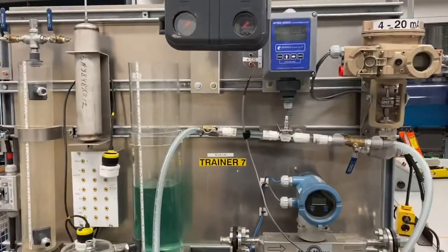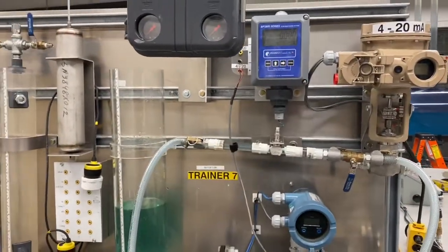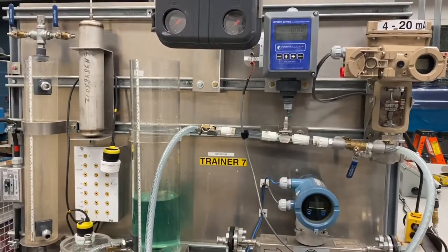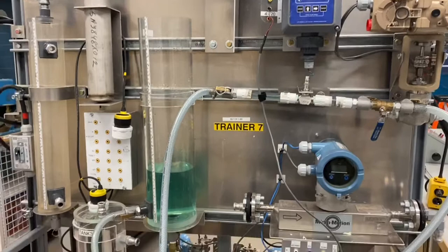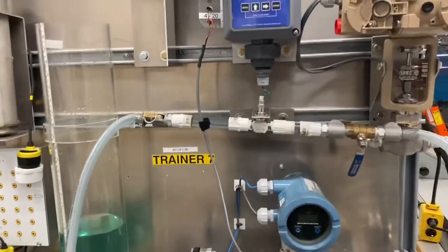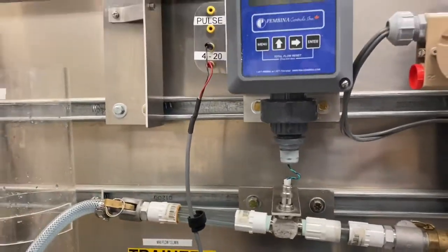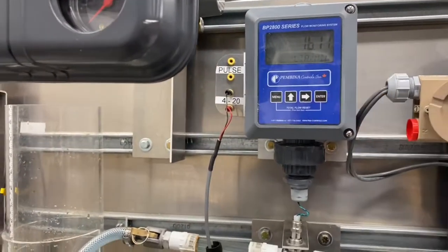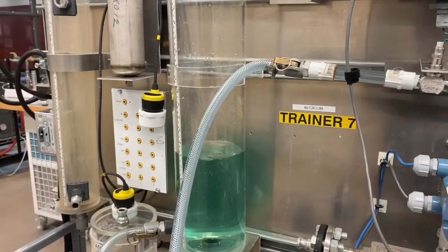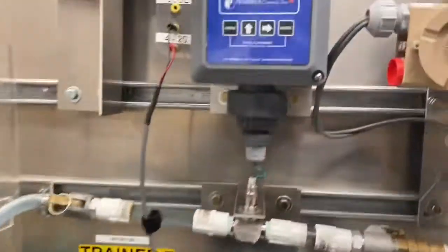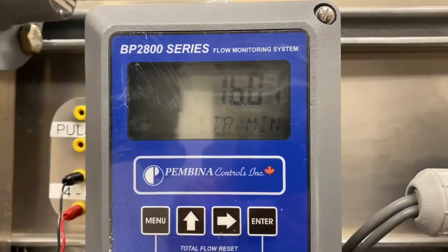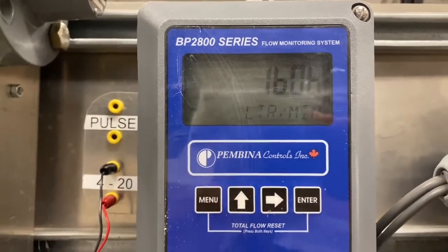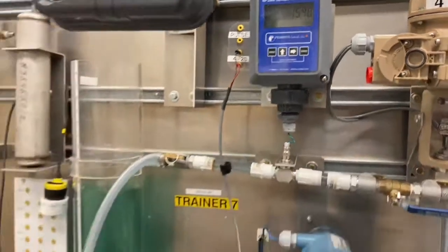The last step of this lab, I've calculated the K factor here based on the average K factor, and I've entered it into the totalizer now. You guys are going to figure that out, so I'm not going to show you what the value is. And I'm just draining the tank down right now, but I'm going to go and open this valve. And I've got the meter now set up to display the flow rate. So you can see right now, it's now calculating the correct flow rate. And if we look close here, it's reading 16 liters per minute there. Now, so instead of a total being displayed, I've changed it so it displays a rate.